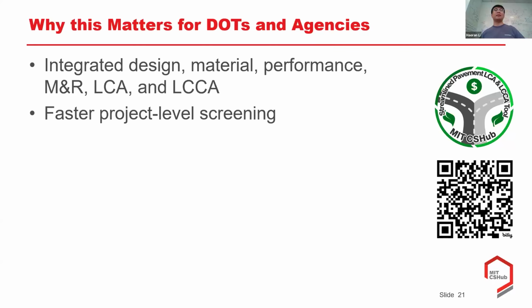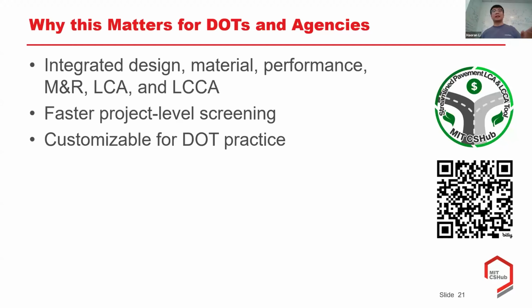We have just seen that, traditionally, if you're just designing pavement using Pavement ME, it takes hours to get a single design. But for these 100 Monte Carlo simulations involving both the LCA and LCCA and also the pavement performance modeling, it just took minutes. And also for DOT practice, we have provided customizable local calibration factors for the performance modeling.